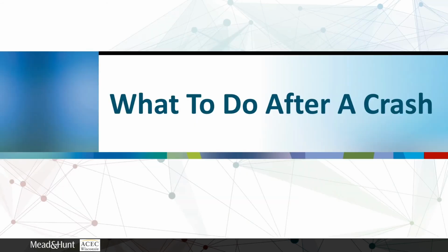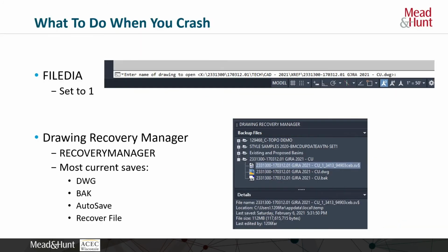Let's talk about what to do after you crash, because it does happen from time to time. The first thing you want to check is your FILEDIA variable. Make sure this is set to 1 so that you have the proper pop-up dialog box to then choose your file in a window instead of having to type out the full path in the command bar.